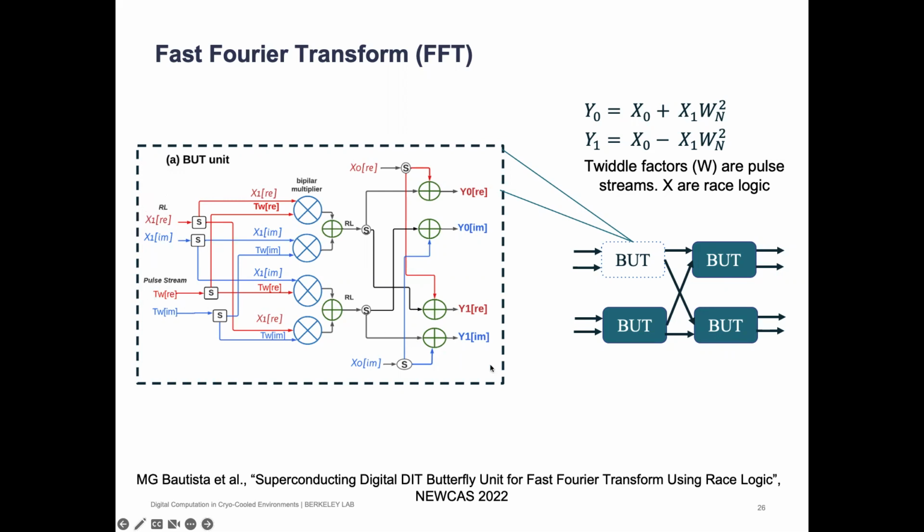That's plenty for now, but this blown up diagram shows you one block, and we can make the FFT computation scale up using the butterfly structure. That is well known in circuits, but it also lets us scale up easily. So basically, we can implement FIR and FFT using much less area than binary, using the principles that I showed you before.